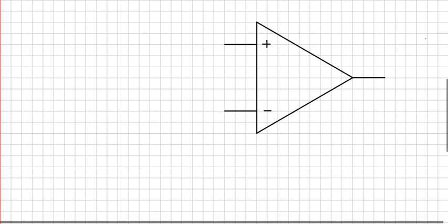So here we have an op-amp circuit, and I'd like to implement the equation that says that I_I equals I_S minus I_F. I'm going to put my I_I on the negative terminal right here. And I want to make an equation which subtracts off a certain current from that.